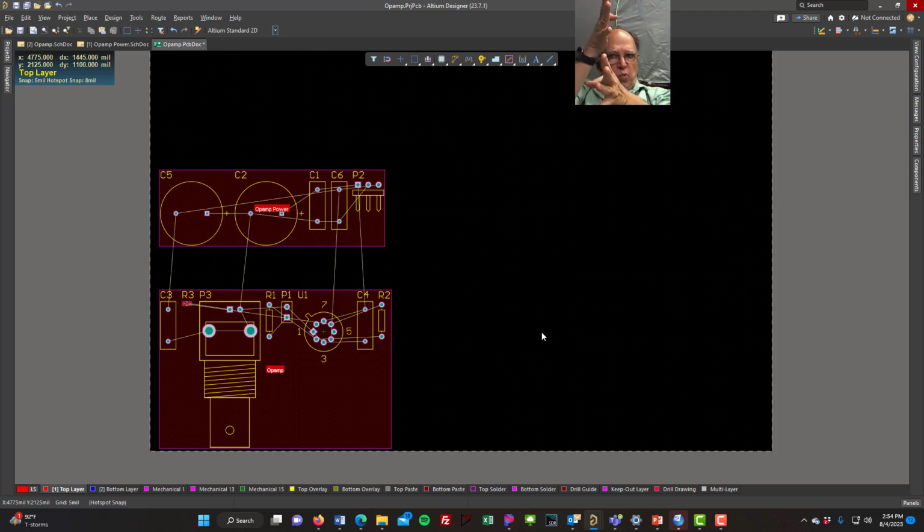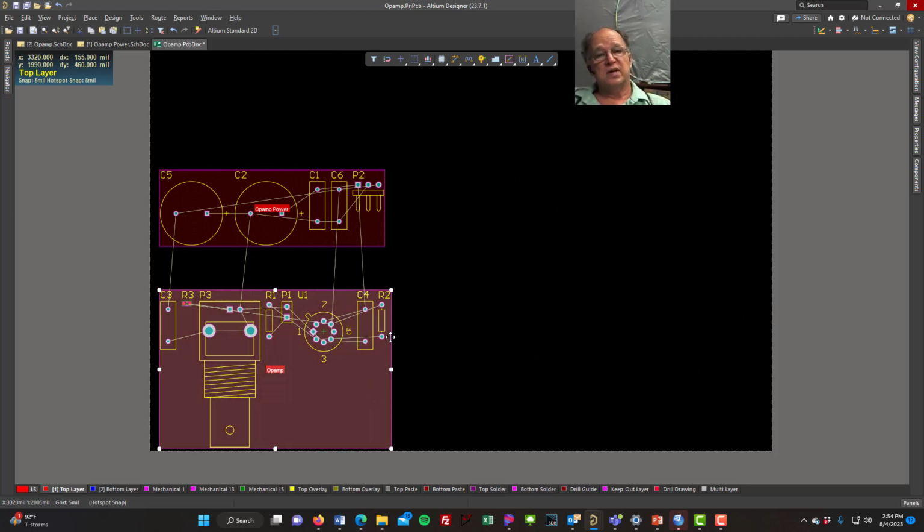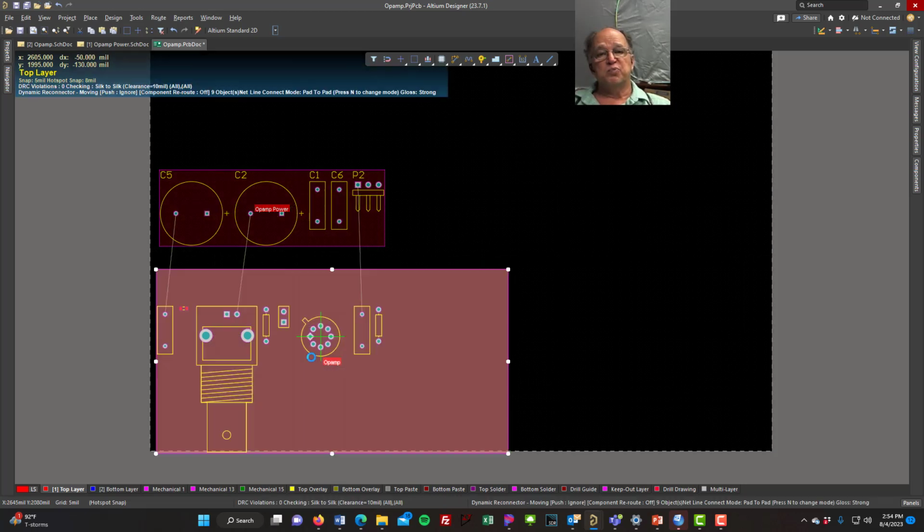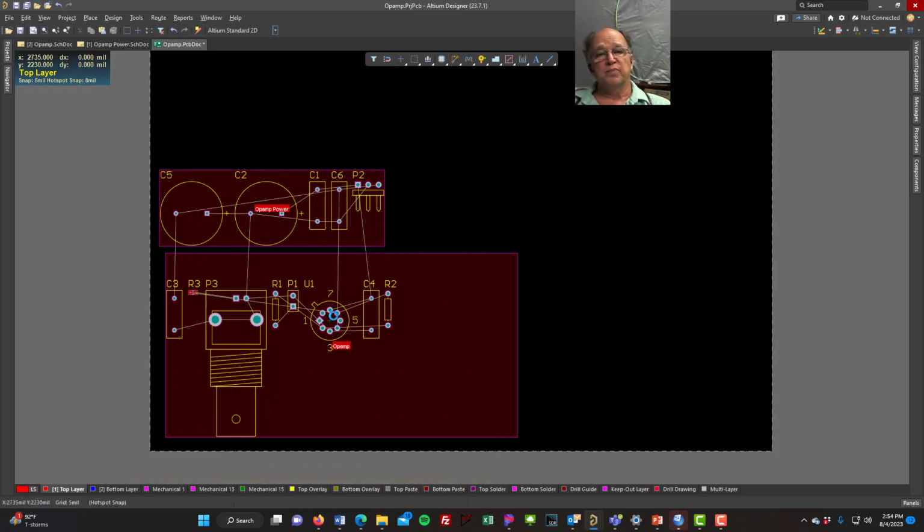So that's one channel. I can draw that channel in Altium and then tell Altium, repeat this 16 times because I want to have 16 channels, and it'll put all those parts into 16 rooms. I can then go to the rooms and say, all right, I want this room shaped like this, and I want these parts inside the room like this.